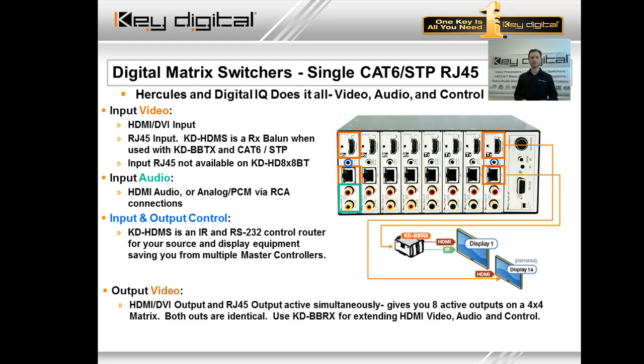Similarly, they might have you hang the display on the wall, you got the cable ran, hey, this is just the guest room, we don't need to sacrifice an independent output, do we? Let's go ahead and just utilize this mirrored output connectivity that is available. HDMI and RJ45 both active simultaneously all the time. Okay, in the commercial environments, this is a huge advantage for your local monitors or for your conference room type applications where they have more often than not 2 displays now, one kind of a peripheral display and one main display.